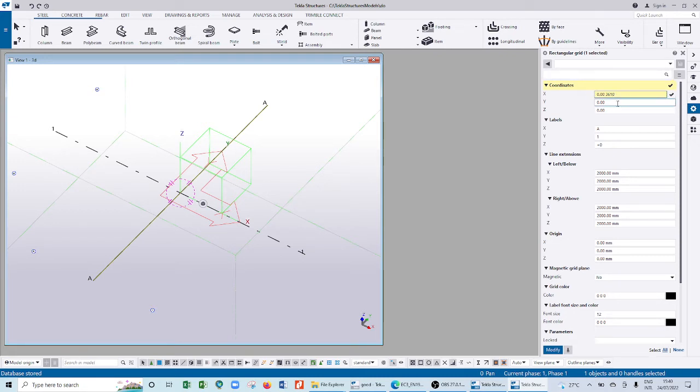Now on the Y, that's the next grid. If I had another grid, I would press space again. On the Y, the same thing: 0, space, then I write 3120. We are there? Then the naming: the first grid on 0, 0 is A. The next one, space, it's B. You type in B. Then in the Y, it's 1. In the next one, space, type 2.